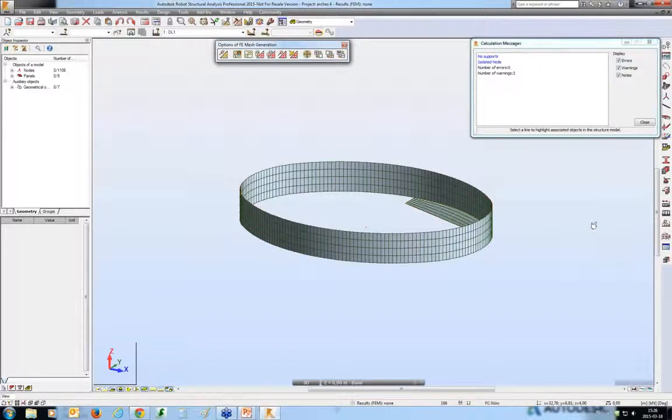And after that, we switched on this reduction option, and I think that's the answer to your question. You may also try to create rigid links from the common nodes of the bar element pile, that's my assumption of how you model it, and the panel, and simply create a sort of rigid surface to reduce the peaks directly over the supports.